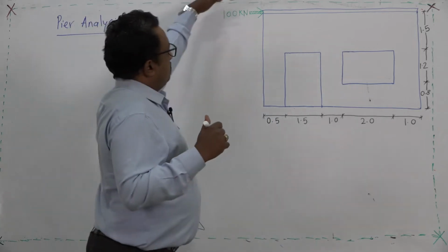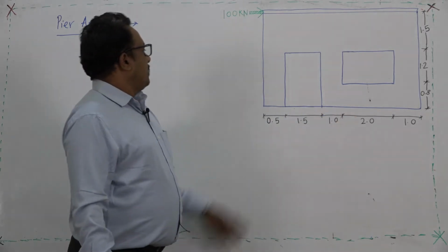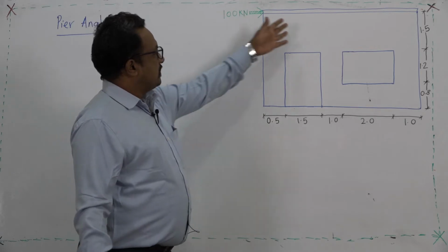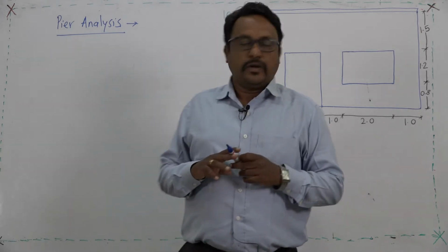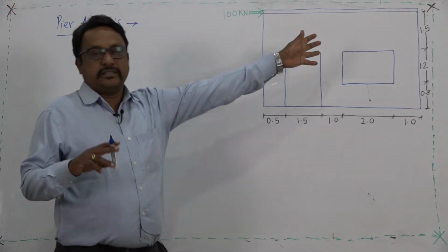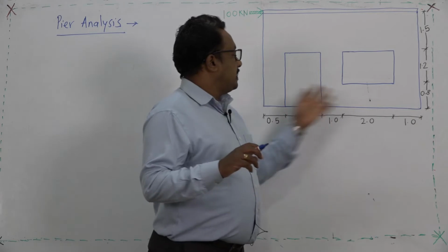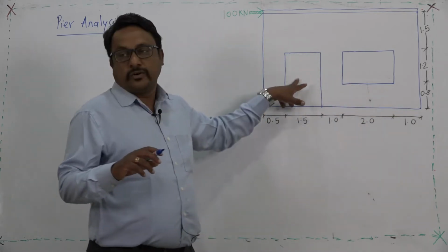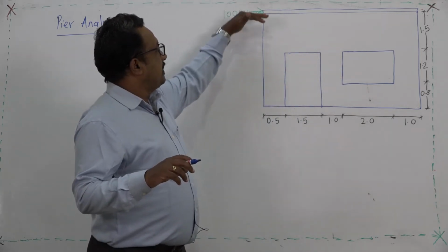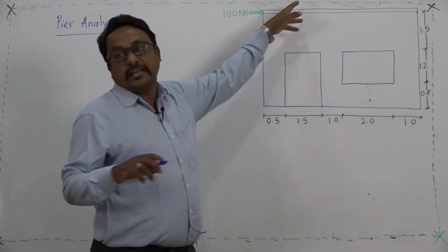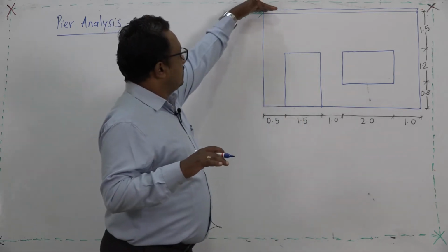The problem we are going to discuss is about this simple building. Here we discuss the problem for a masonry building, but the same is also applicable for a concrete shear wall; only the modulus of elasticity and the thickness of the wall will change. Here the problem statement: we have considered one masonry building, which consists of one door and one window. The top of the building has a rigid diaphragm, meaning there will be a top slab on the diaphragm. So it is not flexible, it is rigid.